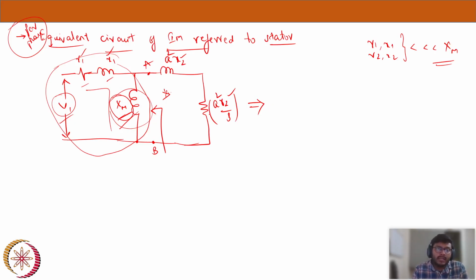And next, the equivalent impedance. So this is R1, X1. The voltage we will short, and R1, X1 in series, and the series R1, X1 will be in parallel to XM. So there we will get the equivalent impedance. So I will just write it here.